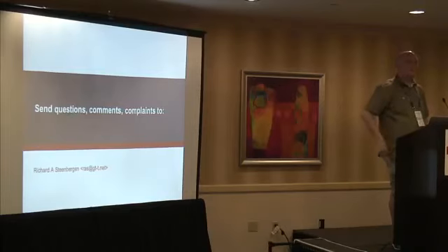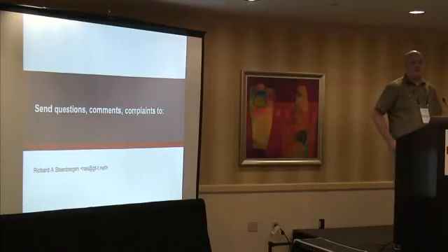So like ZR80K seems like they're pretty close to being mainstream. What's the roadmap for length coming up next? To go beyond 80 kilometer. Basically nothing. So 80 kilometer is about the most that you get out of a single transmitter without doing something like amplifying. FEC is the technique that you use to get past 80 kilometer.